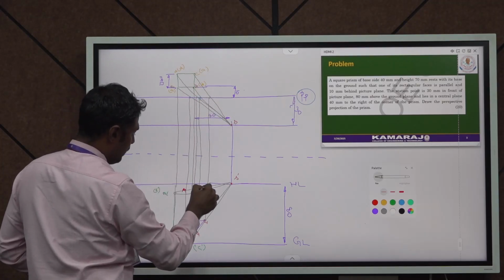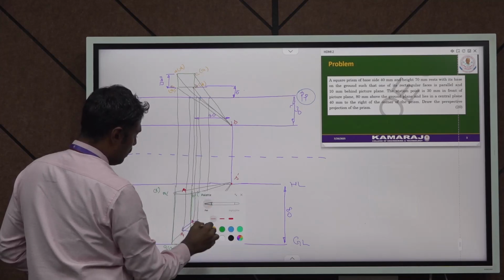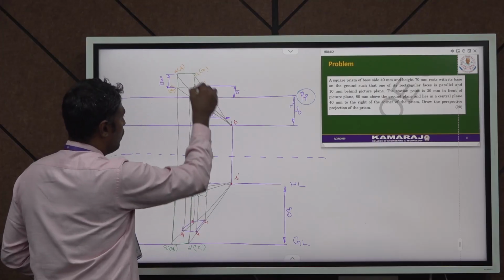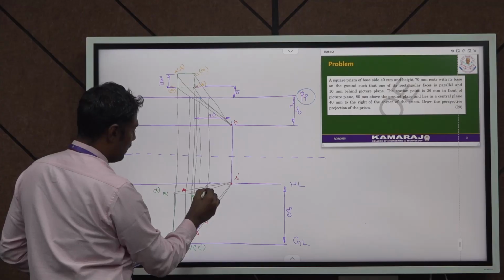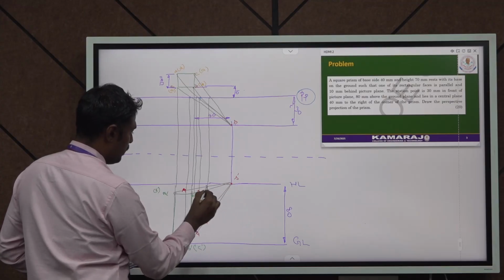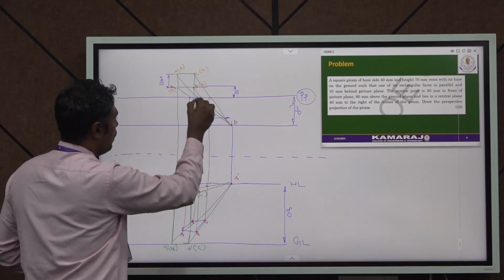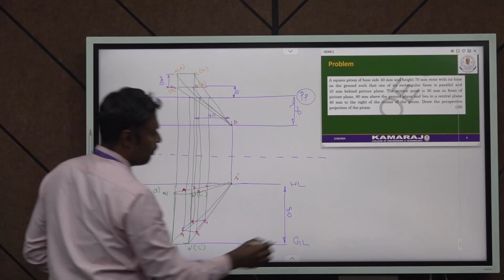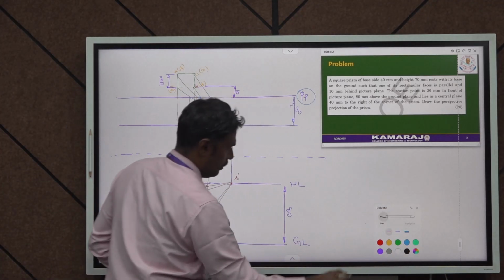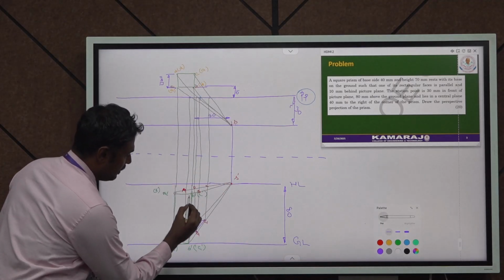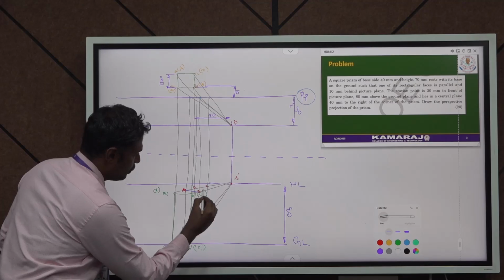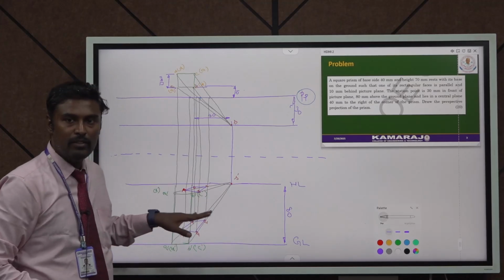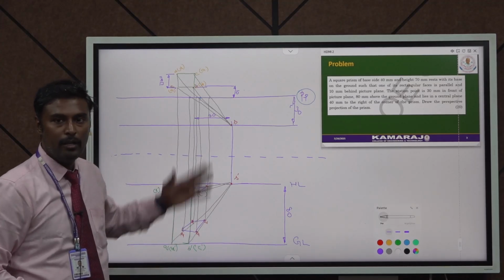The point B is interconnected at this point, and this is point B, and this is for point C. The point C is interconnected here. This is point C, and here this one and this one are interconnected at this point, and this is point D. Now connect all these 4, that is A to B, B to C, C to D, and again A to D. So now the base of the square prism and the top face of the square prism both are completed.